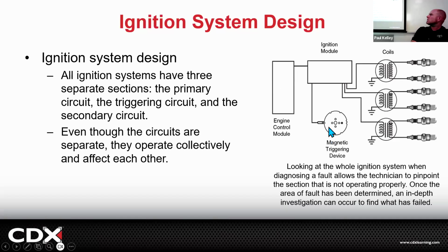Remember how this comes around and it's induced? We could put a magnetic sensor on there and some ferrous metal points on the tooth on the reluctor. Either way, the ignition module needs to get a reference. It needs to know where the engine's position is and how fast it's turning. Then from there, it can fire these coils. It is in the distributor on the old ones.